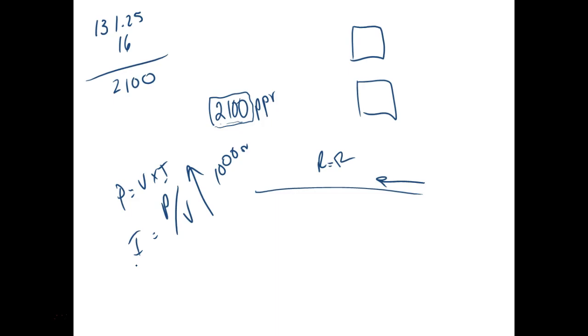The biggest hole you can make and still maintain the integrity of the 2x4, and this is if you put it in the exact center, is what? What is it? 3/4 inch. That's the maximum hole you can put, I think. You have to be in the center, too. You can't be off to one side. If you're off to one side, then you change the integrity of the 2x4. So 90%, probably 99% of the wiring in your house runs through the 2x4. Right? You understand? And you're trying to run a 3, 4, 5 ton unit out there, right? Needs 2,400 watts of power, right? And you're trying to run that wire through your walls.